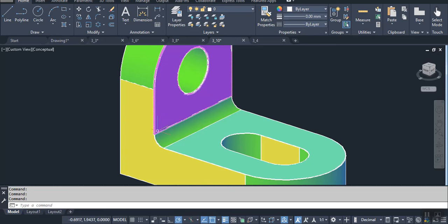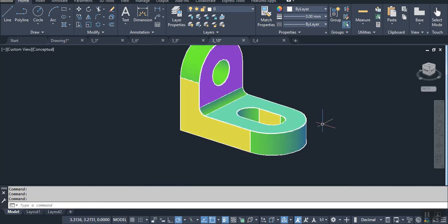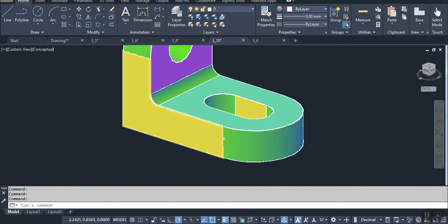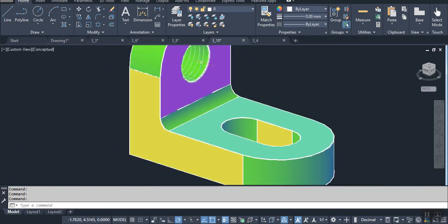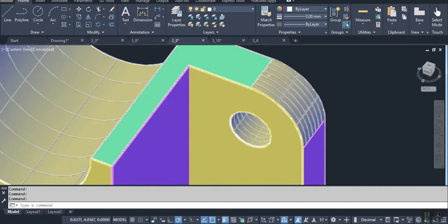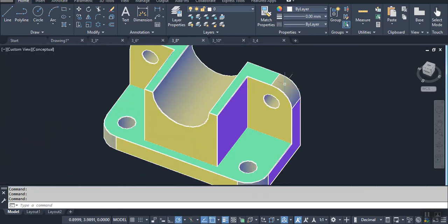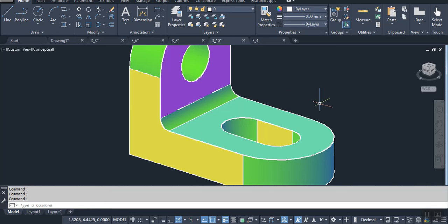This point right here does the same thing, where it goes from flat surface to curve. It adds an edge, and I'm here to tell you those edges don't exist, so don't put them in your drawing. Same thing out here. Same thing here in the slot. It goes from curved, and that's the point of tangency, to flat. It adds an edge. So CAD systems add an edge to indicate flat to tangent arc. We don't when we do the technical drawing. So please don't add them. They are going to make your solution incorrect, and we lose points if we include them. So nothing with curved tangent edges, please.